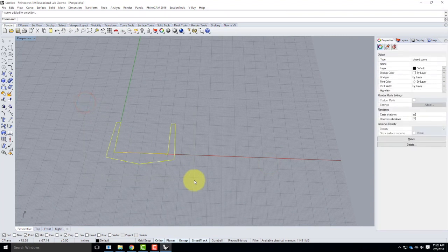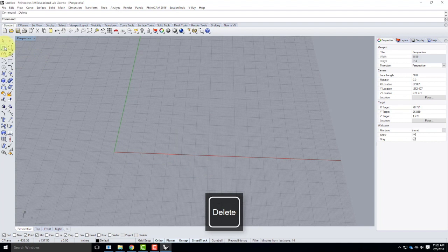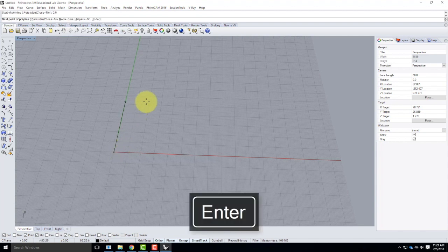So I'm going to do that shape one more time. I'm watching where everybody is. Okay, so let's try it one more time. I'm going to start this at 0, 0. So I have the polyline tool selected. I'll start at 0, 0. I'm going to go up by 36 inches. So the distance is 36, and my direction is straight up the y-axis.